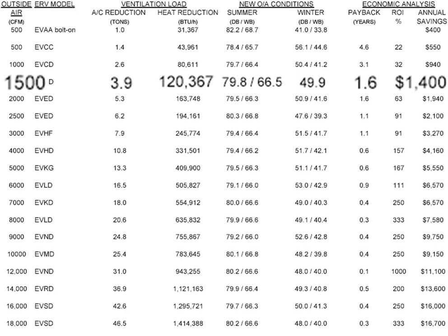I can take a much more extreme example, 12,000 CFM of outside air, which is huge. I got a 31-ton reduction in the size of the rooftop that I need. So if I used to need, whatever, a 70-ton unit, now I'm going to buy a 40-ton unit. Almost a million BTU smaller on the heat exchanger, 0.1 year payback, literally a 1 month payback basically, right?